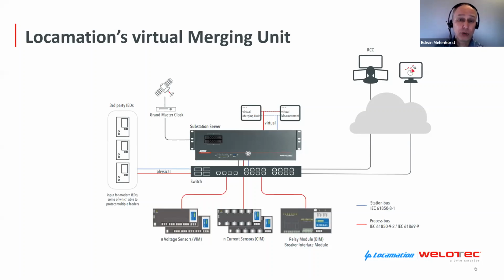The virtual merging unit itself is running on a substation server, again a commercially off-the-shelf industrial computer, and will provide the calibration and adjustment of the process data. The published sampled value streams are then ready to be used by other third-party IEDs, or in the future, virtual applications running on the same substation server.